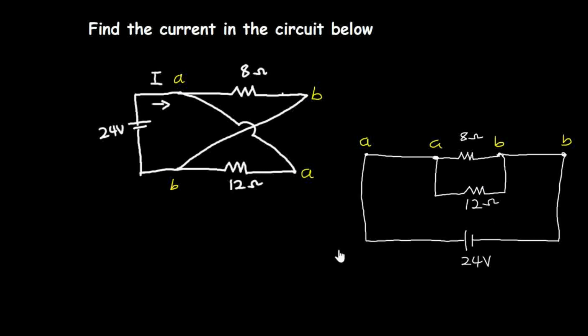So how are you going to do this? To calculate the effective resistance for resistors in a parallel connection, the effective resistance will be the inverse of the sum of the inverses of each of the resistor values. So that will be 1 over R equals 1 over R1 plus 1 over R2 plus 1 over R3, and this continues.